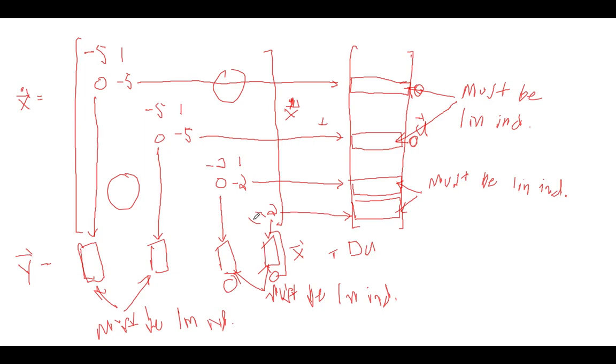So we're going to use that same Jordan form not only to look at dynamic response, not only to look at stability, but also to look at controllability and observability in a very intuitive way that for an engineer lets you actually think how to fix your system and make it controllable or observable when it's not.